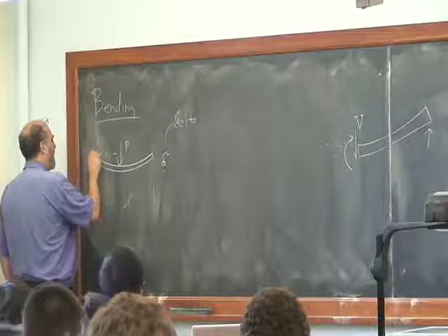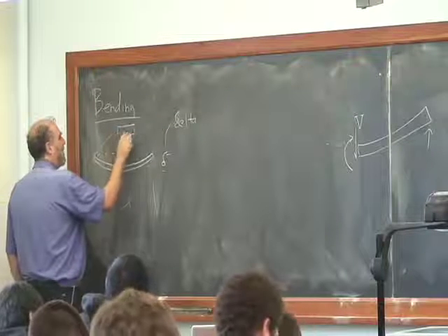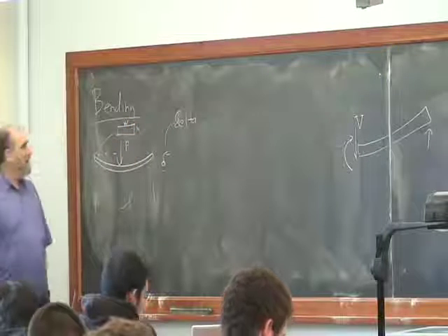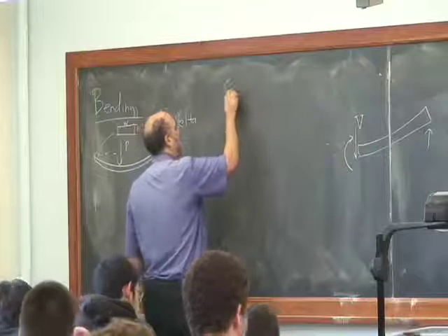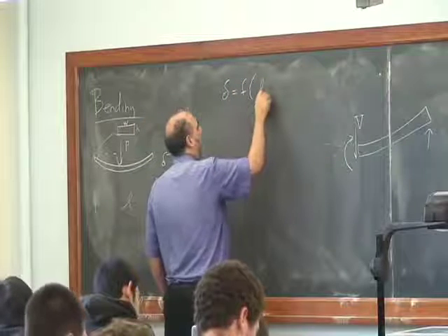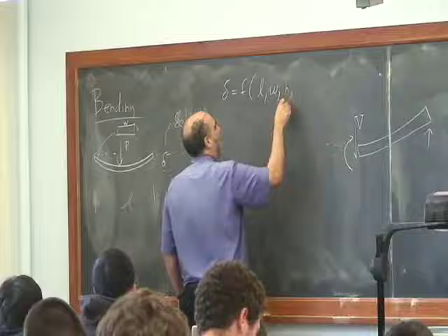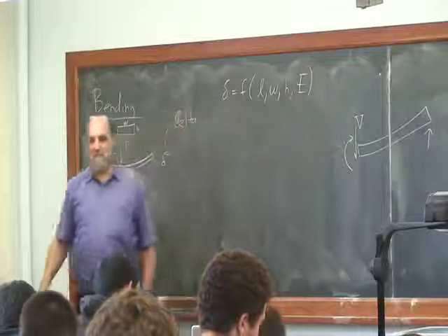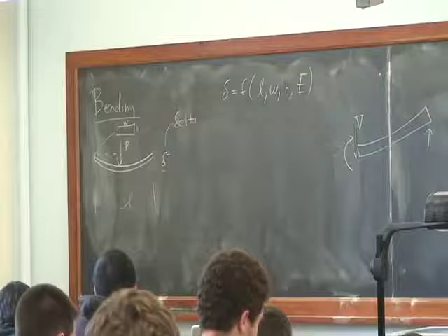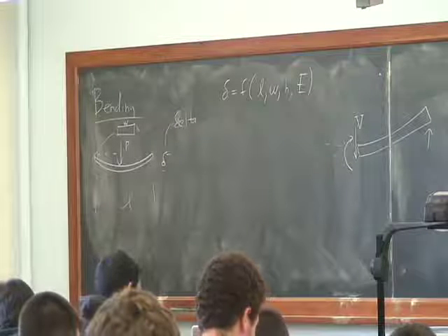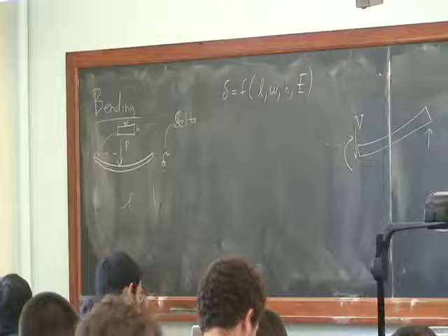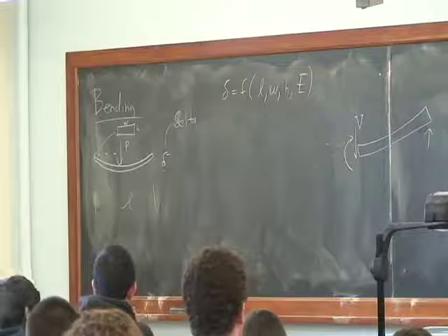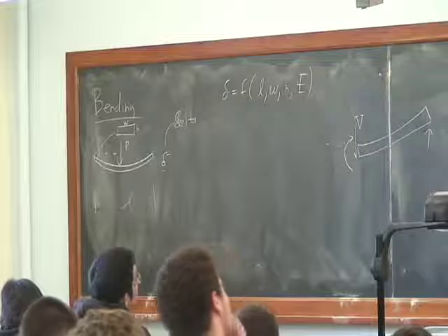And then the cross section of this has some width and some height. So what we'd like to find out is what delta is as some function of the length, the width, the height. And now I'll jump ahead and note that the important material property is the Young's modulus. It's the intrinsic stiffness of the fibers. We'd like to figure out what that formula is, and we'd like to figure it out based on this cartoon that we have so far.